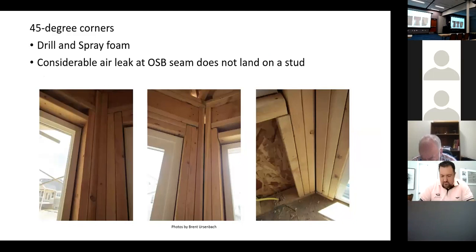So here's that 45 on the corner of a bay. You can see through to daylight and nothing. Here's a 90-degree corner. How are you going to insulate back in there? So would you recommend a solid piece of wood? If you want to do the right thing, you take solid wood and do a trapezoid piece. Well, I think I'd just spray foam it. Yeah, frame it up and rip something down and wedge it inside. I'd just spray foam it, and that seals it too.